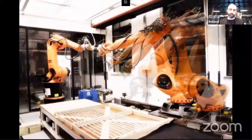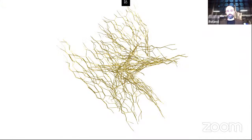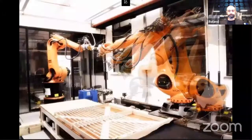I should say with that project, it was very rapid to fabricate. We were able to fabricate all 270 brass rods in a single day. The problem then became one of assembly. It took 5 people 5 days to assemble and weld this project together. So we realized we were really optimizing the wrong thing. We were optimizing fabrication, whereas we probably should have been optimizing assembly.